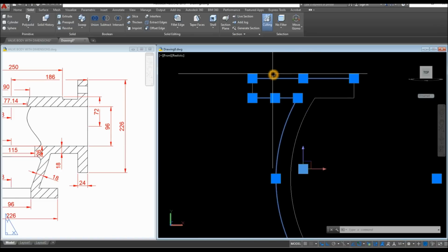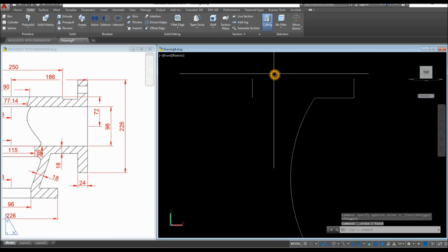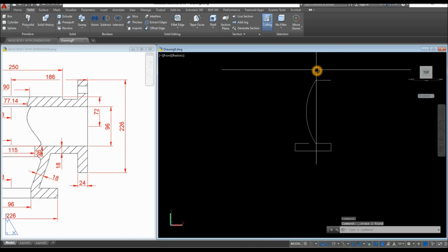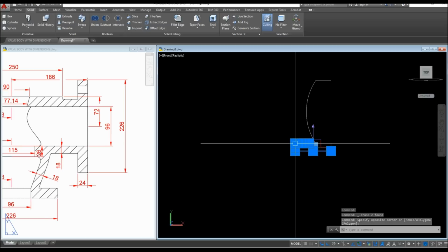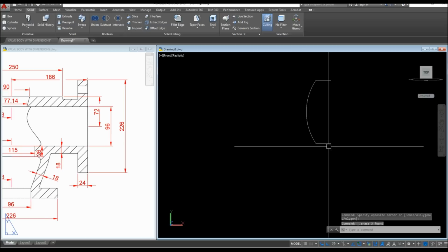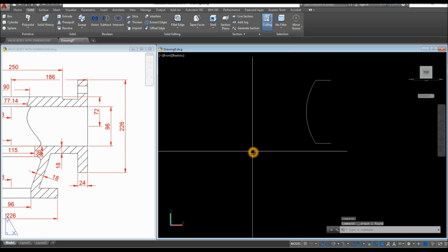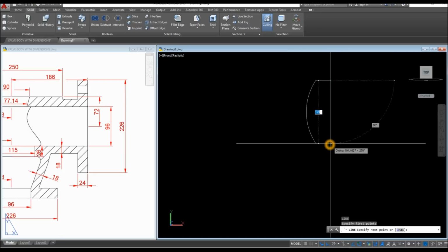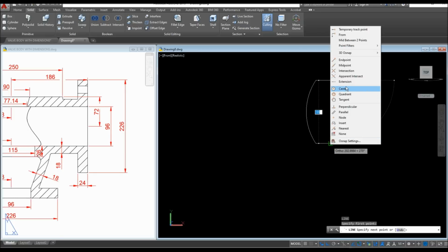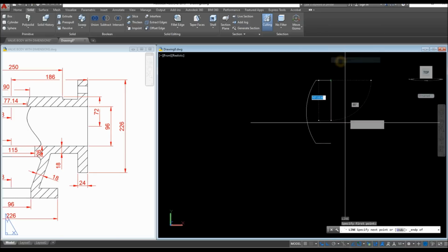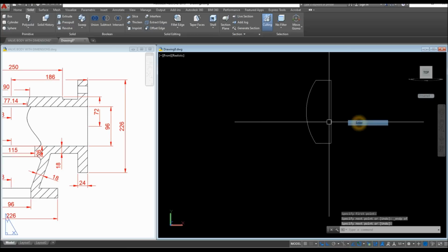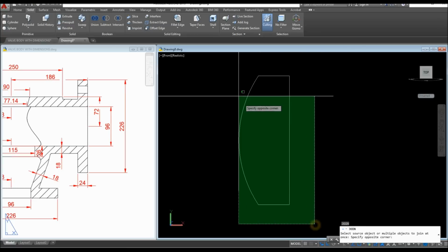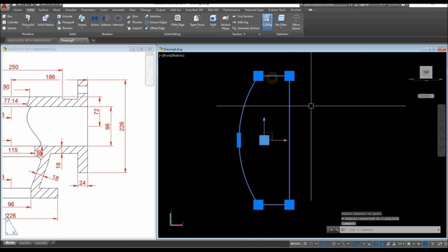So what I'm gonna do is delete those, this one and this one, delete that, and draw a line to connect the endpoints, and snap that endpoint. Now I'm gonna join the segment, so J for join command, and just window the whole thing. Now this is one object.